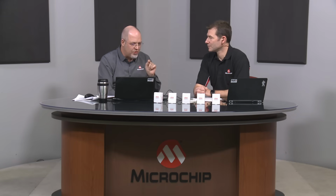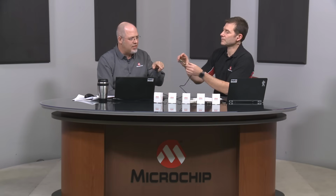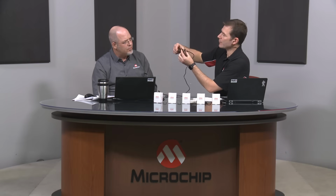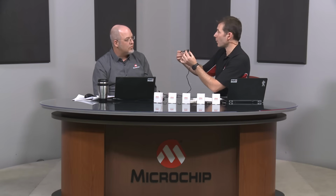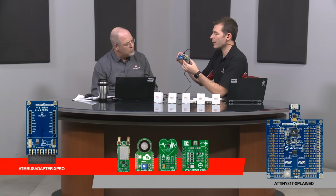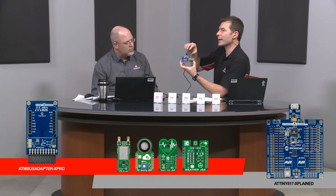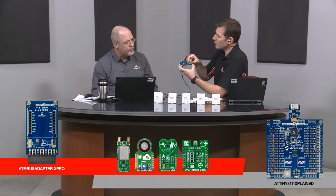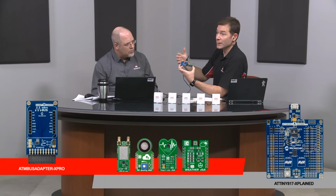One other thing that we should probably mention before we move on is just the micro bus expansion header that we have connected into the board, the attiny 817 Pro board here. So here, I'll just turn it around so you can better see it. Here we have an extension board, so that is just an adapter board actually, but that board is then identifying itself to the host controller here, to the embedded debugger on the system. So in that way, when you connect this board, Studio will not only recognize the baseboard, but also the extension board. Very nice. Unfortunately, it doesn't recognize the micro board that you have on top here, but it does recognize the rest and helps you then set up your project in Studio correctly.